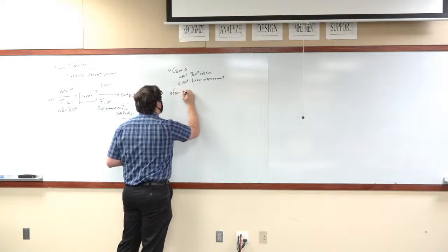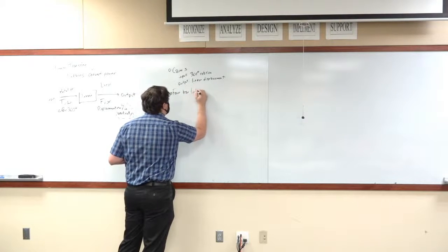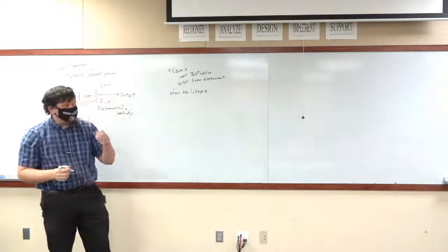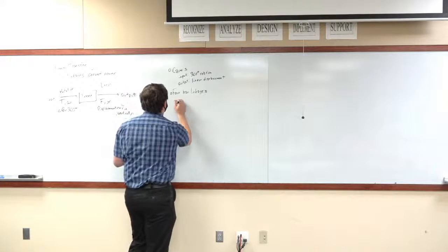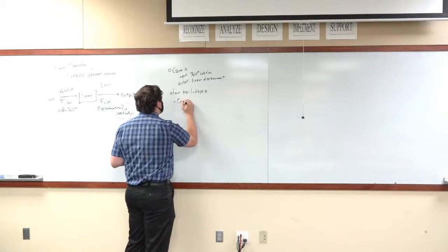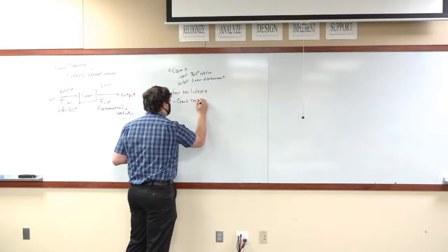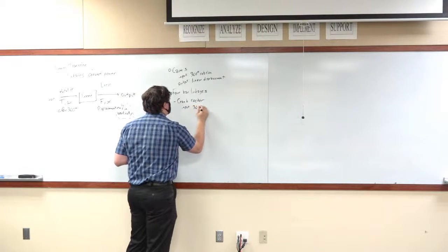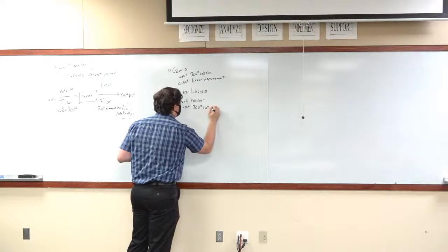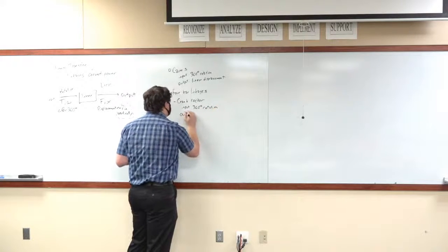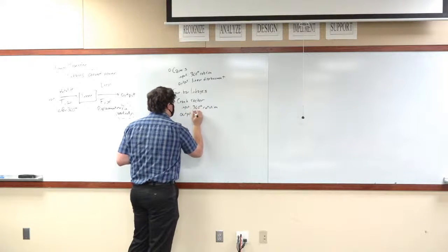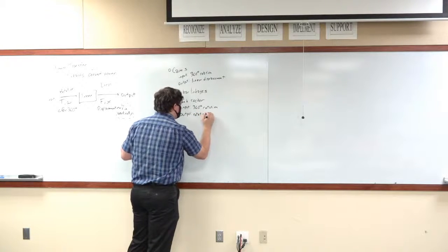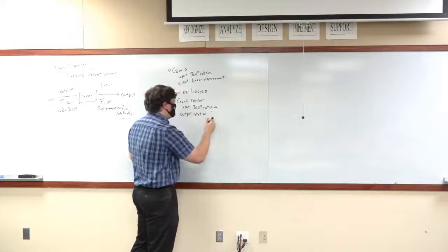We also talked about 4-bar linkages, okay? And there are different kinds of 4-bar linkages. You all did the readings. One of the kinds of 4-bar linkages is a crank rocker mechanism. And for a crank rocker, you input 360-degree rotation, and you output a rotation about an axis point that is a fixed angle.